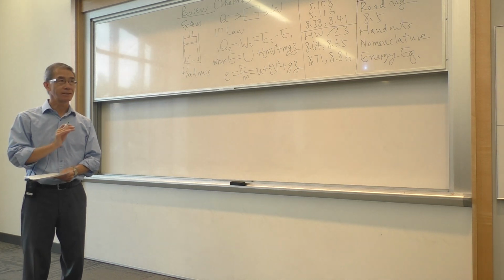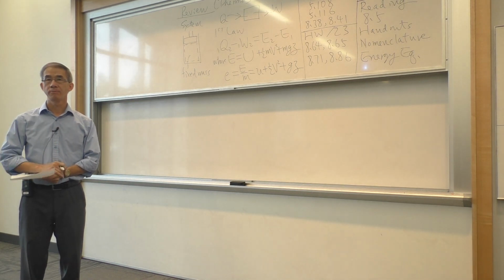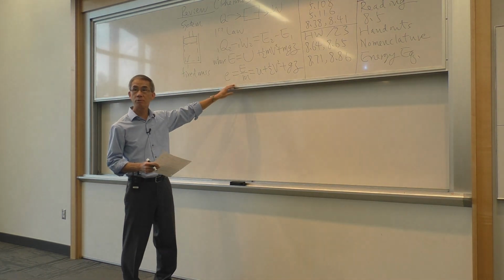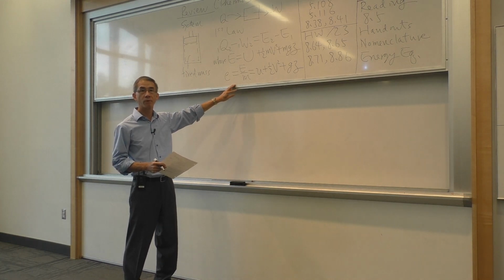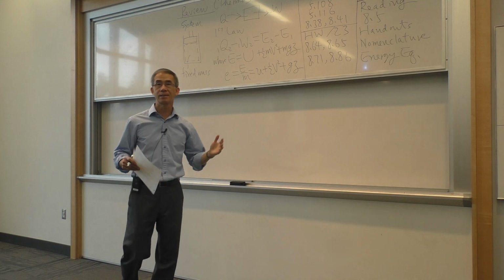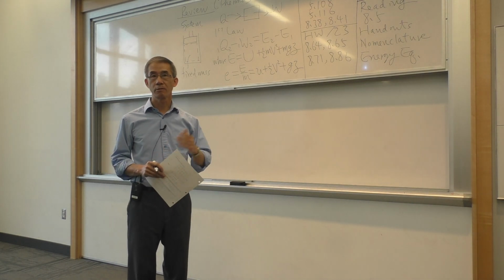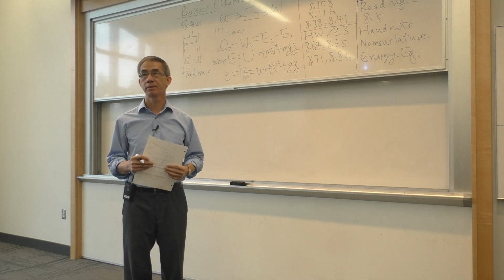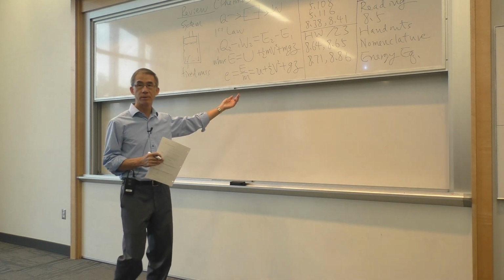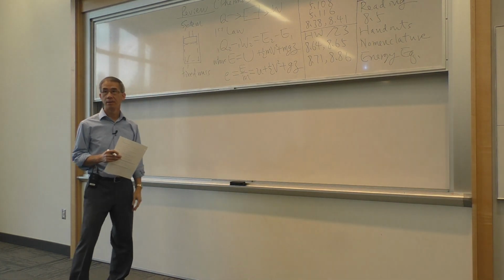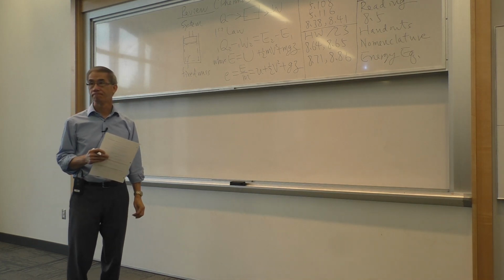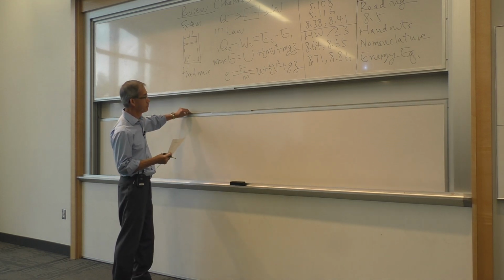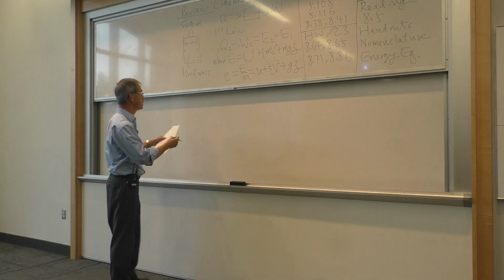So in fluids, we look at it a little differently. I don't know how you have handled that in your Thermo 1. You need to transfer this system equation to a control volume so you can work the energy equation for a device that has flow coming in and out, like a turbine, like a pump, like a boiler. Not a system, but a device with flow coming in and out, a gas turbine, an IC engine, etc. So that's what we are tasked to do now. The way we'll approach that may or may not be the same as what you have done in your thermal class, but they are consistent.